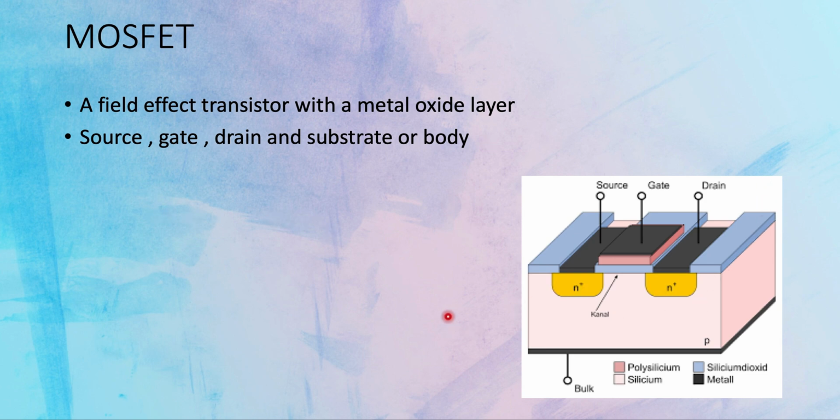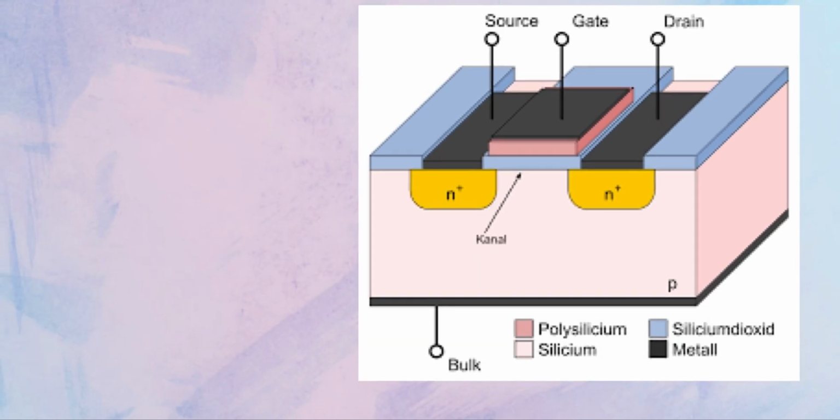Take a look at this picture. This is an example of a MOSFET. So we have the gate, drain and source, and these are the metal layers, and this blue color over here is a silicon dioxide layer. Let me zoom in for you. Now these are also of two types, as we saw, N-channel and P-channel. It's the same. Whether the holes or the electrons create the channel determines the type. So we have a silicon dioxide layer and a metal layer over here.